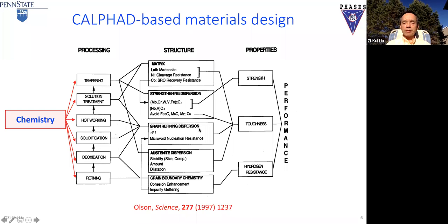What are the structures there? We're talking about, in material science, the phases. You have the matrix phase, like martensite, or you have the strengthening phase, which are the carbides in this case, or you want to control the grain size, make fine grains, or sometimes you need a larger grain for copper properties. Or then the metastable phases, austenite, right? It's metastable, so how to distribute it, talk about stability. But actually, if you enrich it enough, it becomes stable, right? So this metastable stability is really changing because it will change composition.